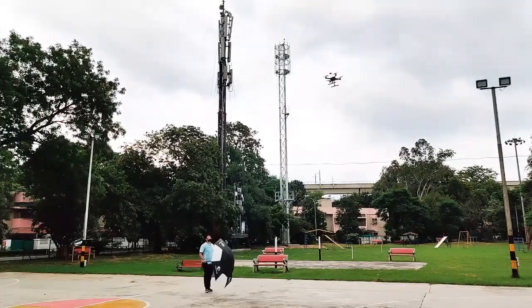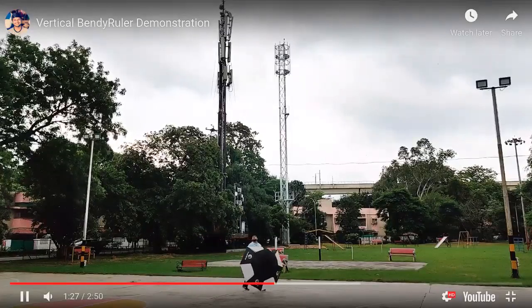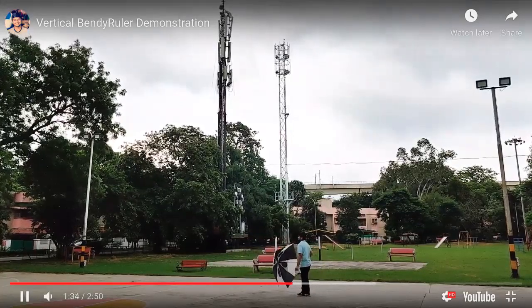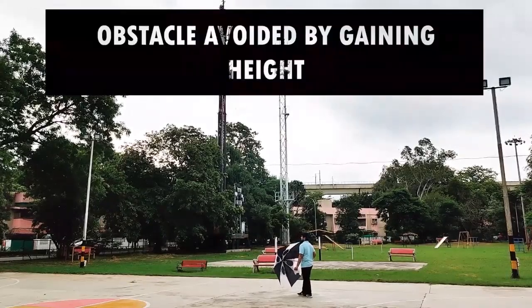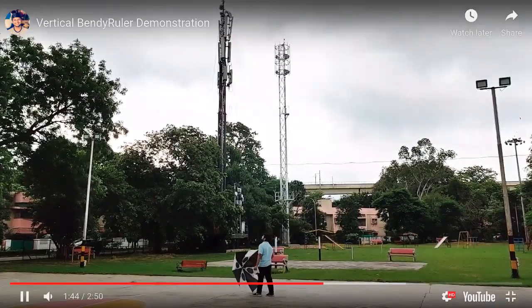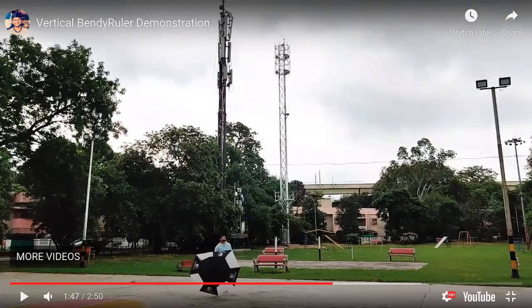Yeah. So it climbs up, and it dodges the person, and it climbs down and resumes its original path. So if you're in, say, a farm or somewhere where there are low plants below you, or if you prefer climbing up, then this is the feature to go with. The basic difference between this and the horizontal bendy ruler is that it just searches for a free path vertically instead of horizontally. That's the only difference.